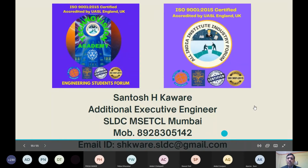When we use digital electronics in the power system, especially for control and protection, then it is a DCS system, digital control system. We use it for controlling, and even for protection you can use this system, because many of our relays are based on electronics. Previously there were electromechanical relays with moving parts, but now relays are static, meaning all electronic components are used. So that is a DCS system.